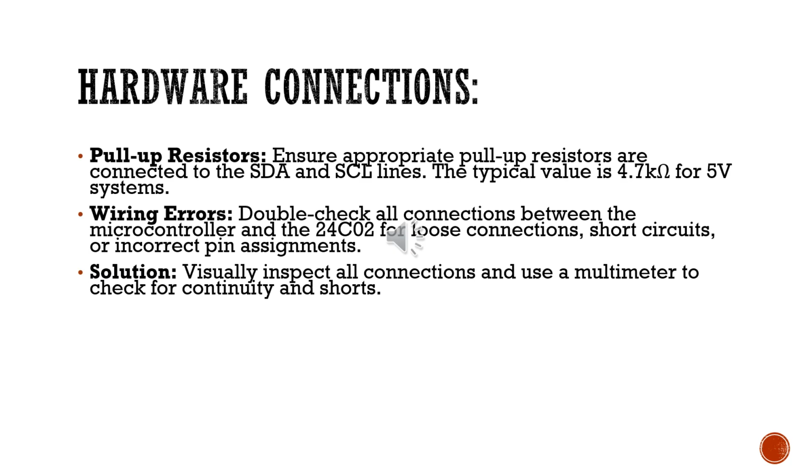Hardware connection. Pull-up resistors. Ensure appropriate pull-up resistors are connected to the SDA and SCL lines. A typical value of 4.7K for a 5-volt system is used. One can work around with 10K resistors also.